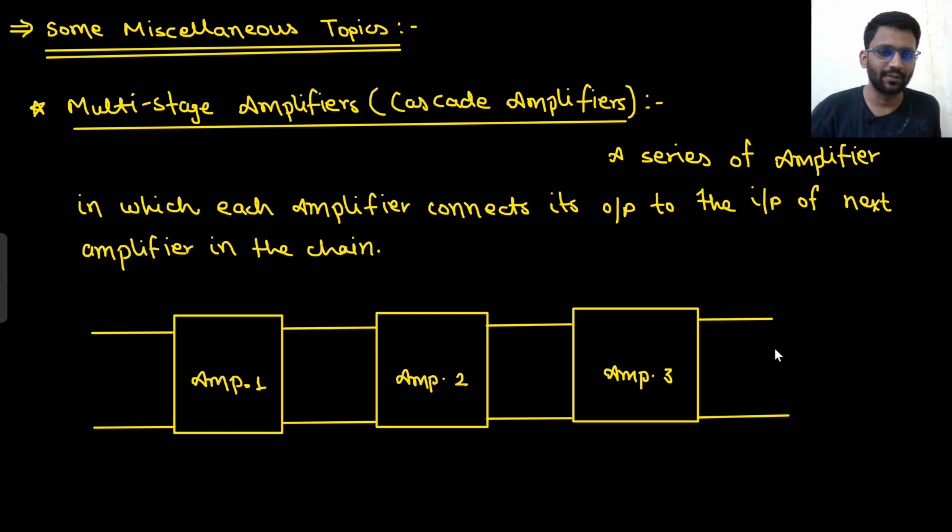This is the gain of the common source amplifier with degeneration. Now, this will not be the complete gain. Why so? Because there will be some reduction in the gain. Voltage division would be there, and that voltage division would be R1 parallel R2 upon R1 parallel R2 plus Rs. And this is the gain, GmRd upon 1 plus GmRs, and the negative sign is certainly there since this is a common source amplifier. Now this Vx will be amplified by the second stage.